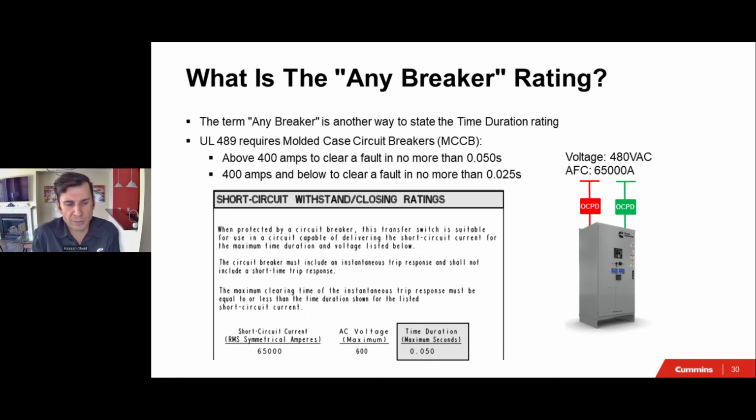So for the transfer switch, when you protect it, you can use time duration, or you can use a specific OCPD, overcurrent protection device. The specific OCPD can be a breaker or a fuse, and those would have to be listed by the transfer switch manufacturer. So when they do the submittal to you as a consultant engineer or to the end client, they'll have that label packaged as part of the submittal, and it also gets attached to the transfer switch itself. But in this case, we have applied the time duration rating.